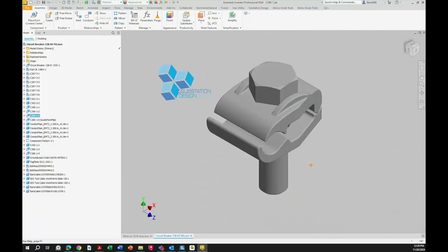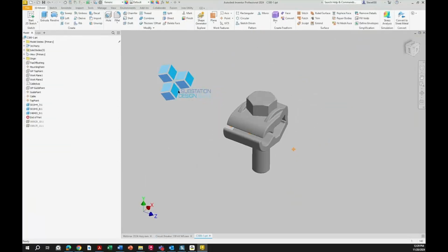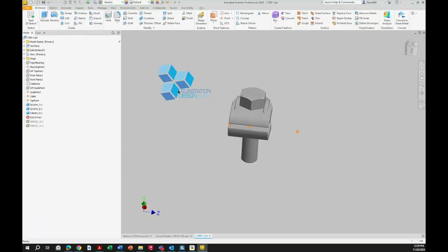We were working with model states here. It's not the same as positional rep, but we can't do positional rep in this because it's a single part. So we're forced to use model states. But model states came in Inventor 2022, and until this happened, we could not do this easily. Anyway, you could do it different ways, but this is very easy now. So here, if you come up here, I got guide point flip. So I have a model state guide point flip. Here's my guide point. It's flipped over here. I go to primary, and my guide point's over here.